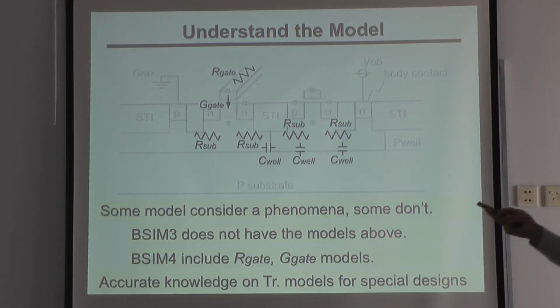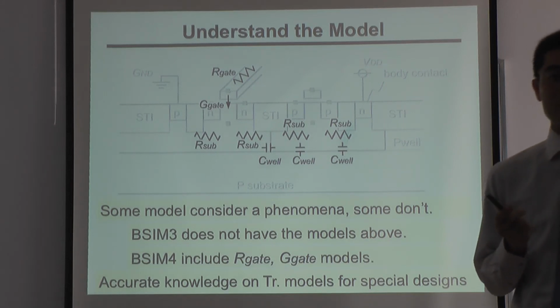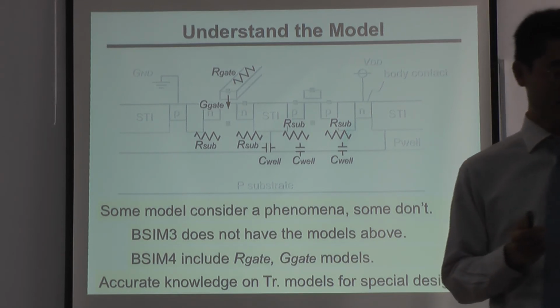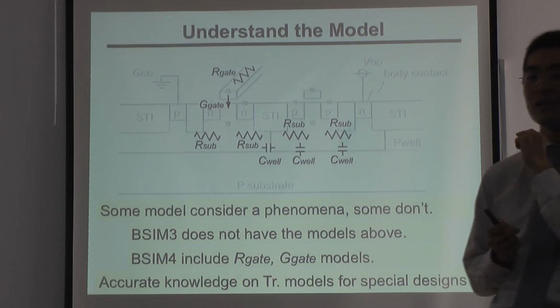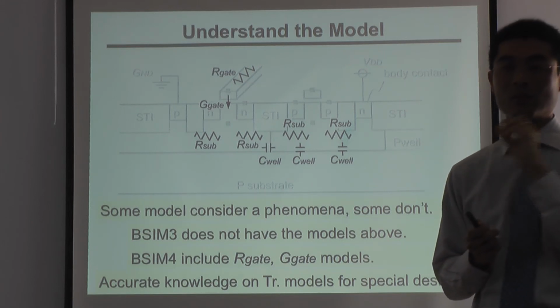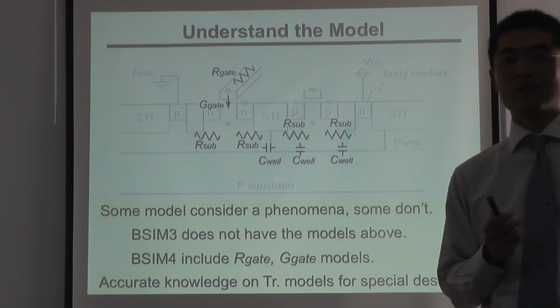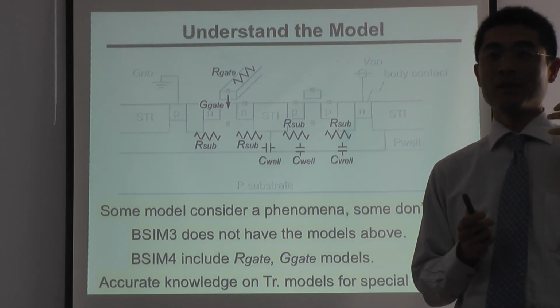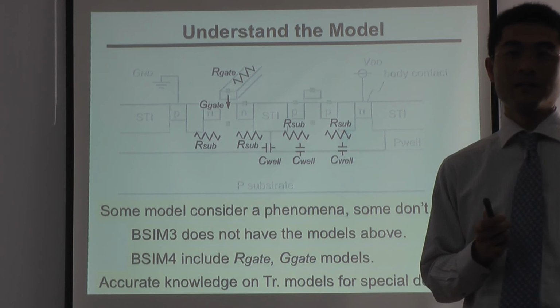And the main difference for our normal circuit designers is the gate capacitance and gate leakage. And BSIM4 takes into consideration the gate leakage. Actually the gate leakage parameters are usually included, so once we put NMOS, it automatically leaks from gate to channel. But on BSIM3 we don't have gate leak.